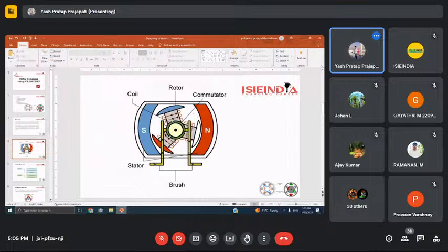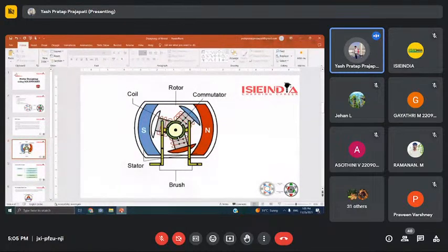In an outrunner BLDC motor, the rotor part that spins is on the outside, surrounding the stator, the stationary part. The design often provides higher torque at lower speeds, making outrunner motors suitable for applications such as electric scooters, model airplanes, and certain types of electric vehicles.